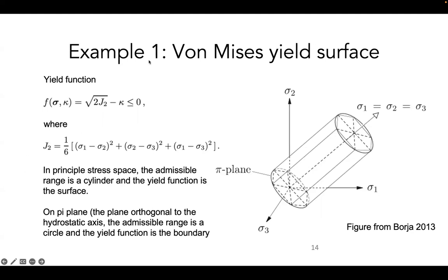This is one example of an isotropic yield surface that doesn't have backstress. You can enlarge the cylindrical object or make it smaller, but that's it. You can control that by changing the radius, so the change of the radius will be the hardening law. The yield criterion would be the Mises stress. And the plastic flow is not given here; it could be obtained by a different law.